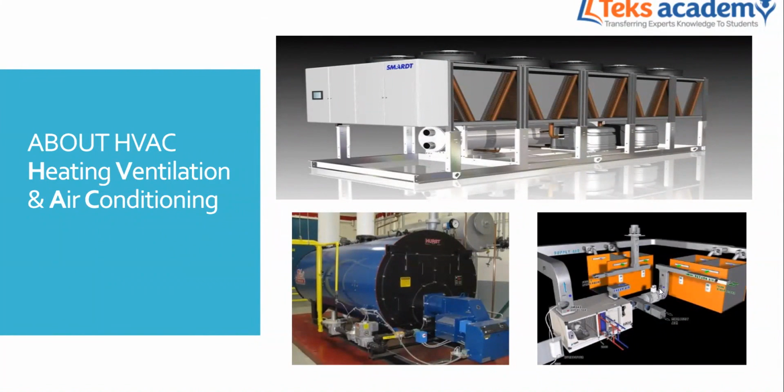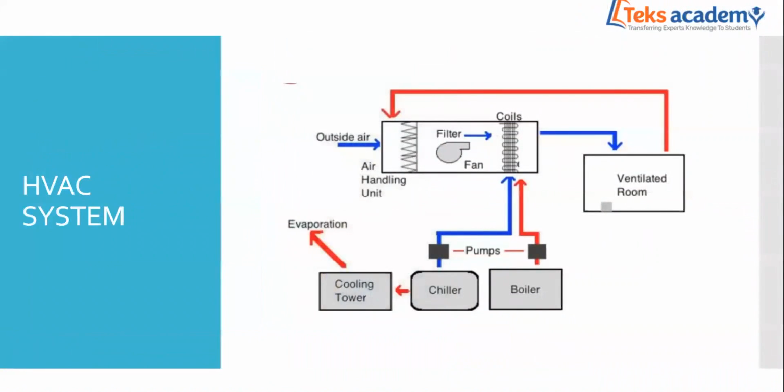The ducts pass all through about the ceiling level, with FCU, VAV, supply duct, and return duct. The system works like this: outside air comes in your duct to your AHU, the air handling unit.